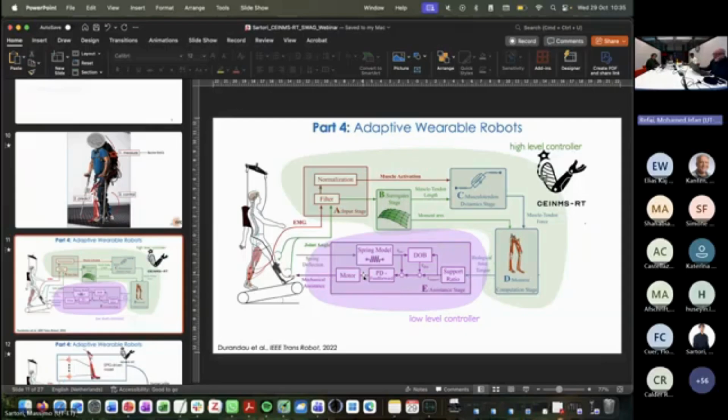Yeah, so in this specific study, and in all the studies that we show, so the ankle exoskeleton, the trunk exoskeleton, and the ankle prosthesis, we use EtherCAT, which is a hard real-time communication protocol to control robotic devices in a hard real-time manner. So we have hard real-time deadlines. But this is only happening at the low-level stage.